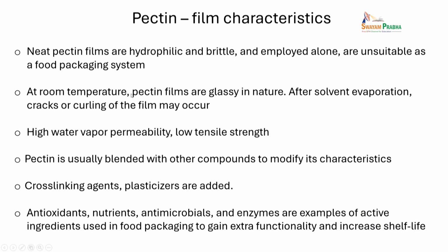Now, if you consider just the neat, virgin pectin alone, you will see that these pectin films are quite hydrophilic, and they are quite brittle. They are easy to tear if you employ them alone. Therefore, they are not actually suitable for a packaging application per se. If you leave a pectin film on the table, after some time it will absorb a lot of moisture and become very sticky.